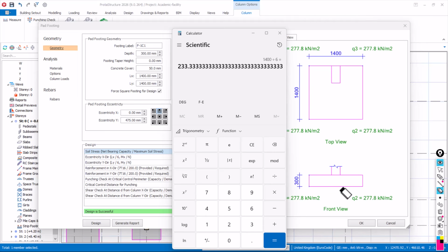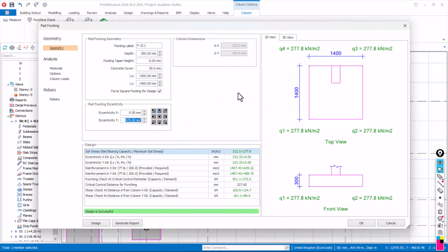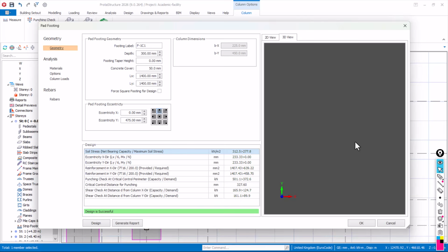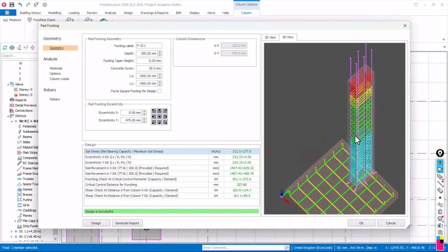Okay, that is fine. So I will now click Cancel here. Since we have this issue happening, this is how we want it to be because of the boundary. If this footing extends further, it will encroach into the boundary area, which we do not want. So does it mean that we cannot design this again? No, we can still design this. Okay, that's fine. And that is what gave birth to a strap beam or a strap footing.